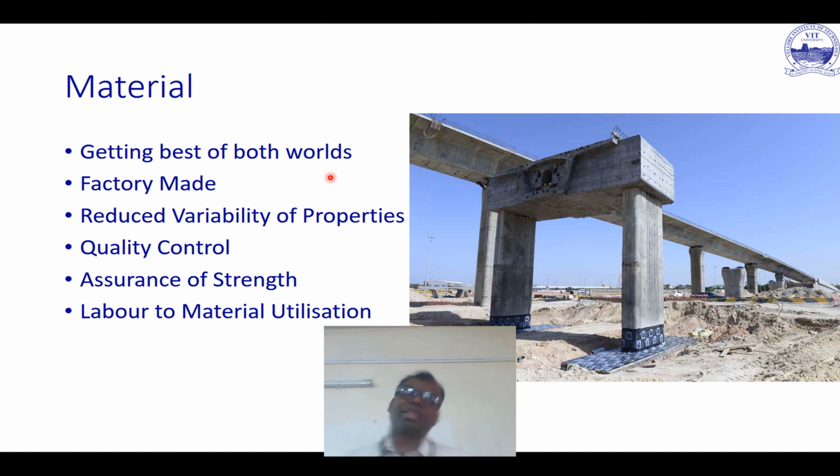You are assured of the strength. Okay, especially when you are putting it as pre-stressed concrete, you are assured of strength. Why? A pre-stressed element has its maximum live load, which it would experience in its life, only at the time of de-stressing. So the moment you cut the tendon and there is bearing of the tendon with the element, that's the time when you get the maximum stress.